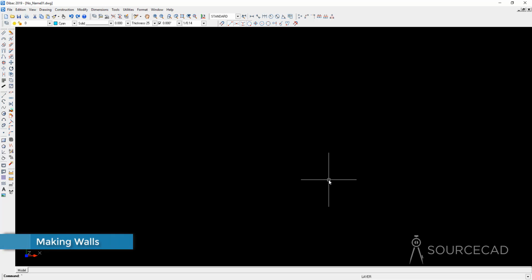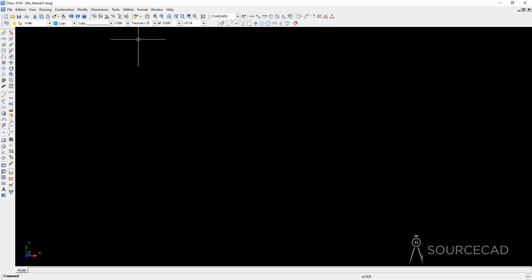Now let's begin making the wall. So now I'll go to this layer drop down and I'll change it to Walls. Also, I'll start by the external walls of 10-inch thickness. So I'm going to select 10-inch thickness here and I'll click on this wall tool. So this is the wall tool. I'll click at a point. I'll move my cursor to the right and I'll type 30 feet.